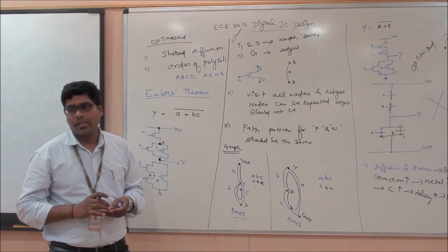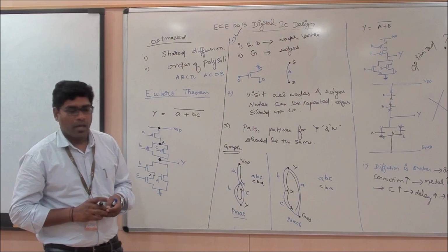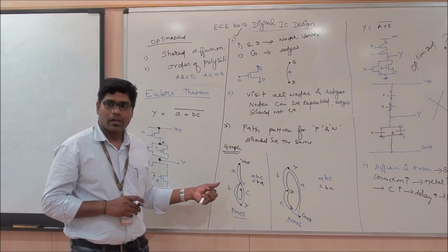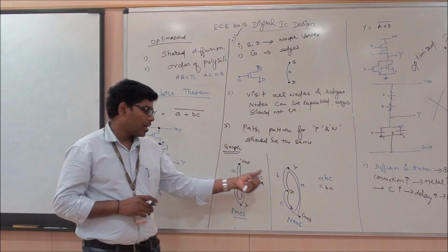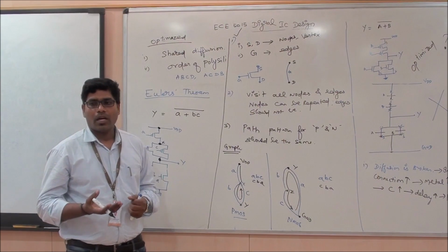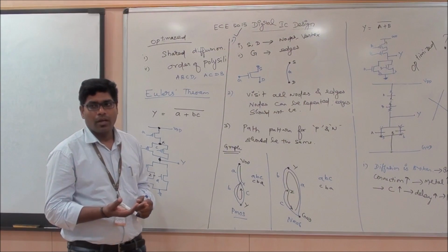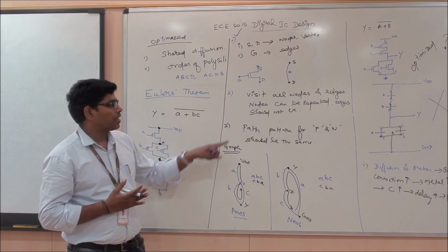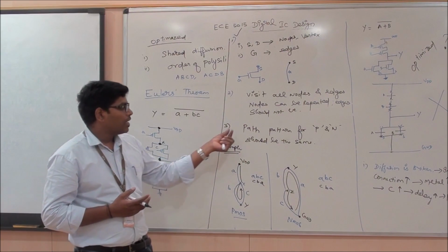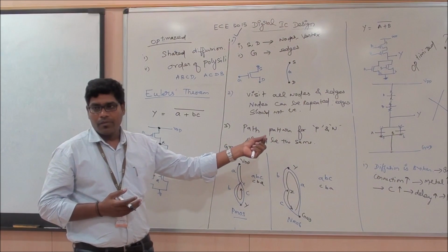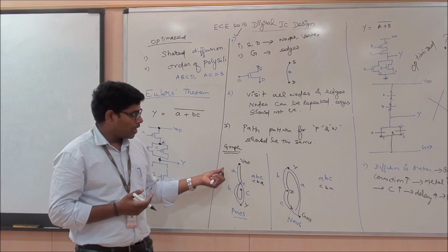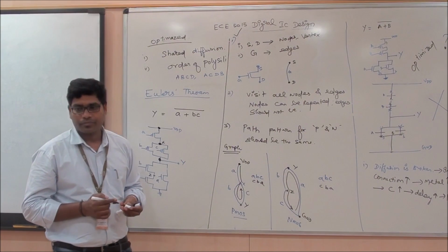But there are some cases where a particular pattern will be suitable for an NMOS network, yet the same order may not be suitable for a PMOS network. Under that case, you are not supposed to use those patterns, because the third rule says use the same pattern which is suitable for both the NMOS network and the PMOS network.